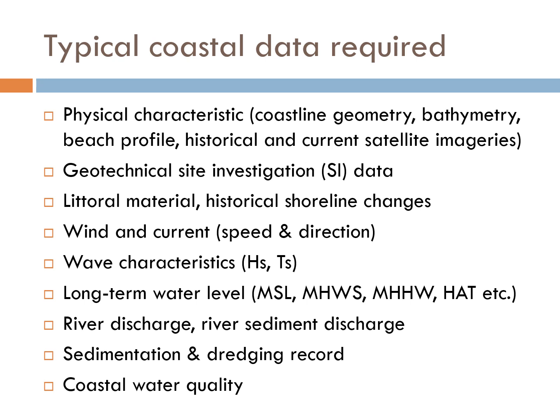Littoral material can be determined based on grab sampling at various locations, so that we have the sediment size distribution, and this can be related to the shoreline changes, so that we can find out what is the net alongshore transport or onshore offshore transport in the particular site area.